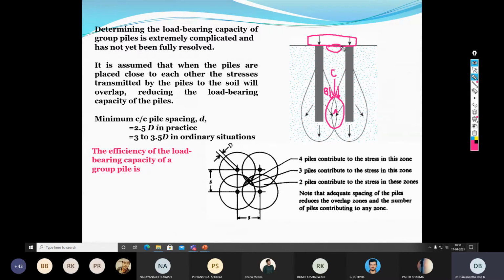Now, when you have designed the pile group, this gap formation has not been accounted for. As a result, the amount of friction that should obviously get developed along the pile periphery might not be developing. Because here, for example, this zone you have accounted for initially in the pile capacity. But because of the formation of this cavity, this might not be contributing in the due course of time. So that means this has an impact overall on the superstructure. So this is how it gets impacted.